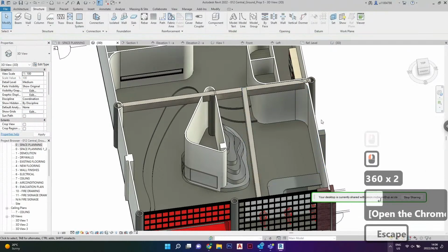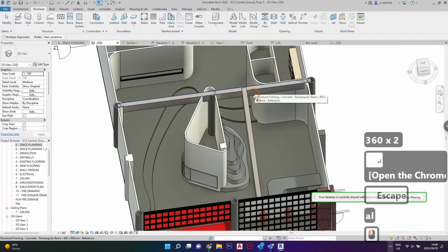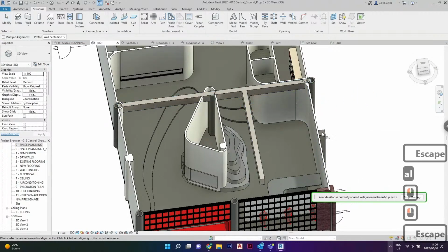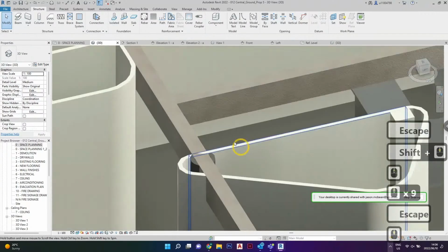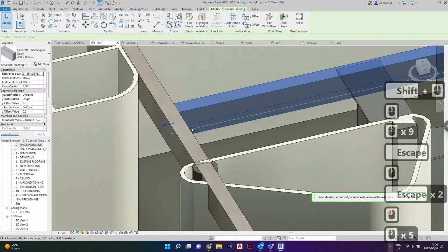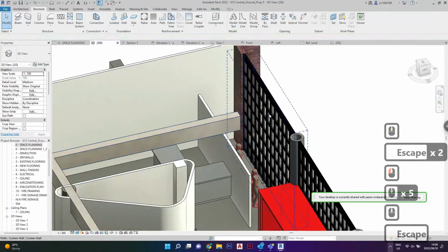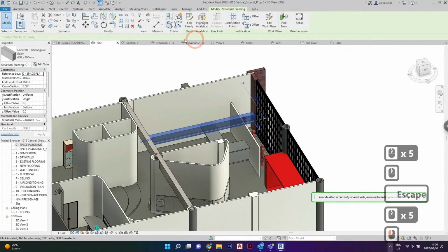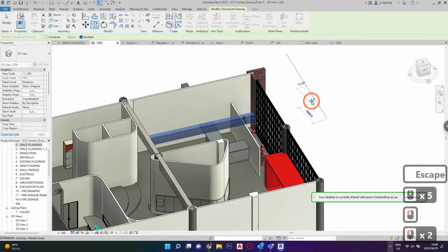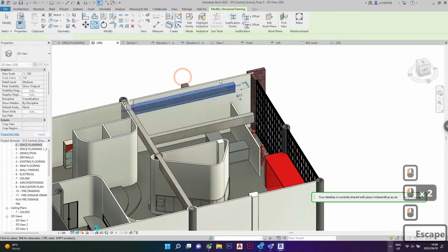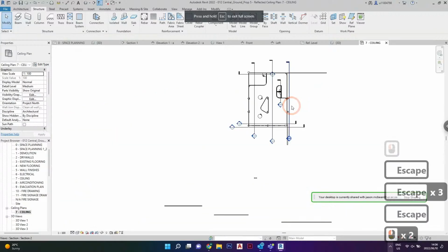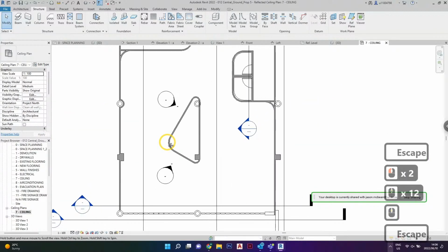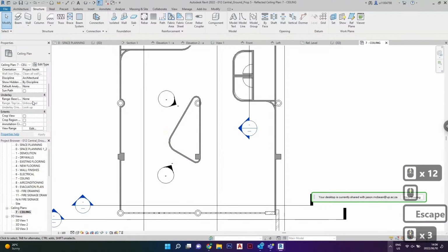But watch this, you can just go align. Check our joins. These beams are designed in a very specific way. They will actually join. And what's neat is, I'll copy these guys just like this and go to ceiling view, and then I'll make these things align. I'll actually work in ceiling view. That's where you should be working. Ceiling view. If you don't see your beams, just increase the view range.